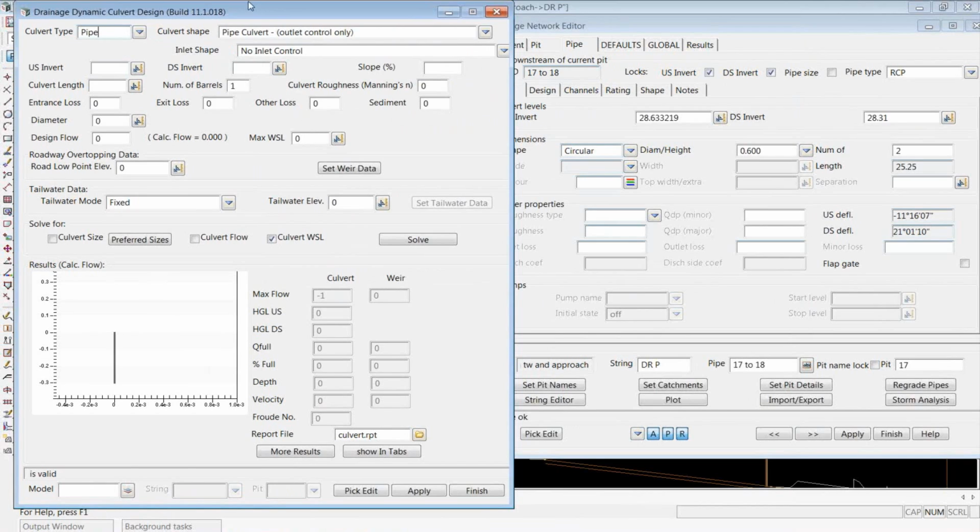Where they start to vary is in the flexibility for additional losses and additional shapes. There's a little bit more that you can do inside the dynamic culvert. So for example, the losses, okay? With the rational method, you can specify your KU for your type for your inlet nomographs, but the entrance loss and the exit loss, or pardon me, just the entrance loss that's used during the hydraulic calcs under backwater conditions are hardwired in. With the dynamic culvert designer, you can change those.